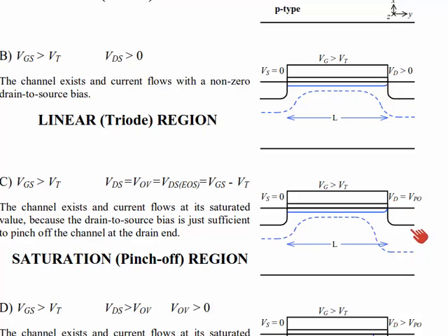the transistor. This pinch-off point represents kind of a point of maximum current. Our current gets limited by the electron's ability to squeeze through this pinch-off point, and I'm doing some hand waving in my language here, but it's not horrendously misleading. If you want to get a better picture of what goes on, you actually have to get involved in solving the Poisson equation in 2 dimensions minimum, and that gets to be a lot of fun, but that we will leave to more advanced coursework.